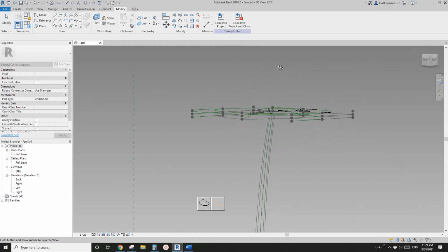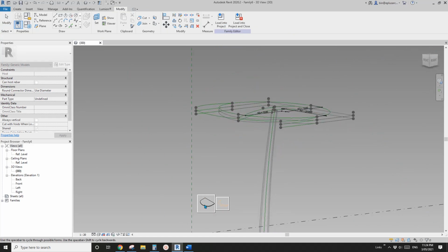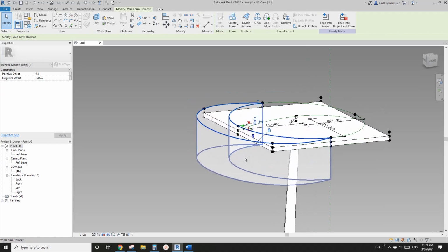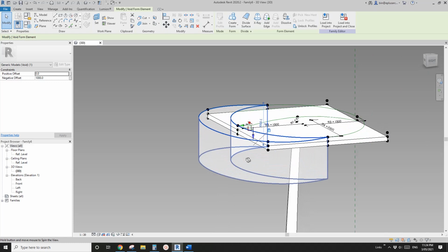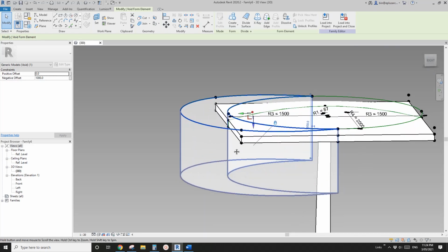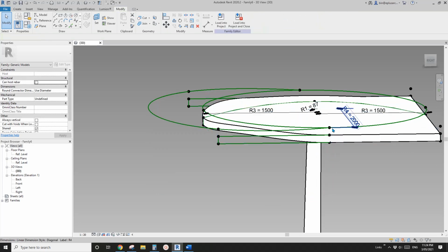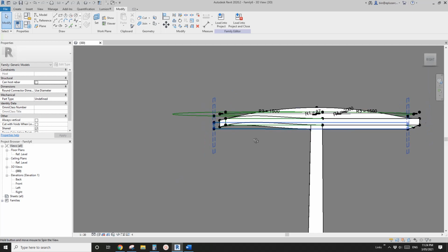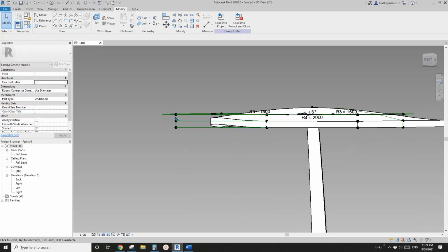And for the void, select this one, the one on the left. So this will create a void, a solid void, and then we're just going to give it a thickness. For the thickness, actually, we just need it from this point to maximum this point, which is the two thicknesses. One is the drop and the other one is, I think that's the drop.